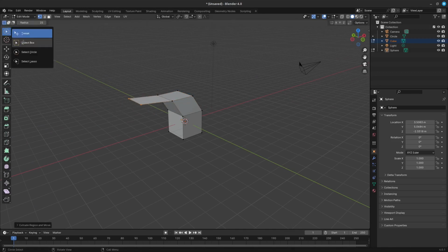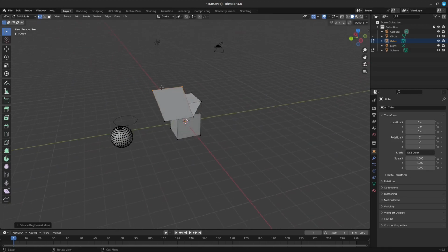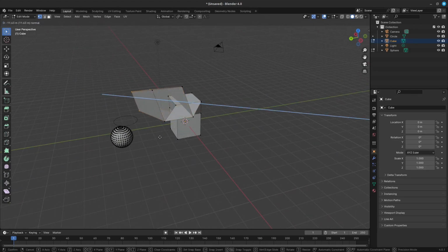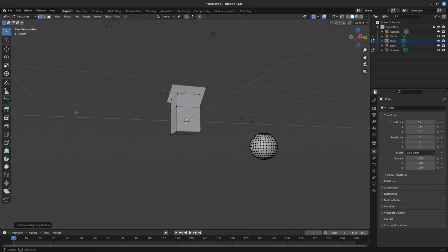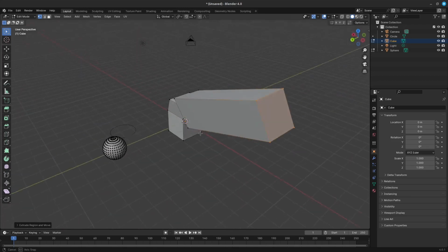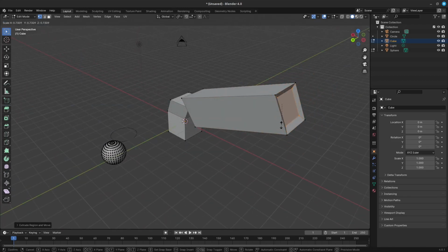It allows you to create parallel pipes from rectangles and cylinders from circles, as well as easily creating such things as tree limbs. The axis on which vertices and edges are extruded along can be set interactively. Faces are extruded by default along their averaged normal. The extrusion can be limited to a single axis by specifying an axis.